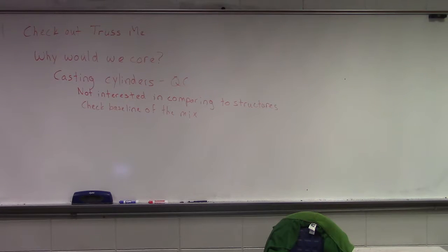Yep, well, let's keep in mind the point of the application, right? It's not structural. If we're talking about patio block, paver sections, or footings for a deck, burning a little bit more water doesn't concern me. But if we're talking about foundation elements for a 50-story tower, we better not be seeing any water going into that truck on the job site without it being documented, to make sure that we aren't exceeding that. We have to control that with our admixtures. So, being mindful of our application.